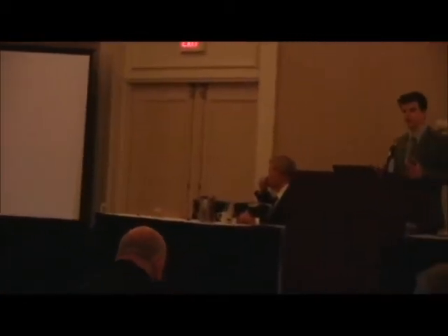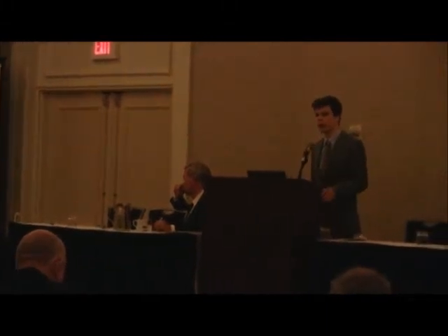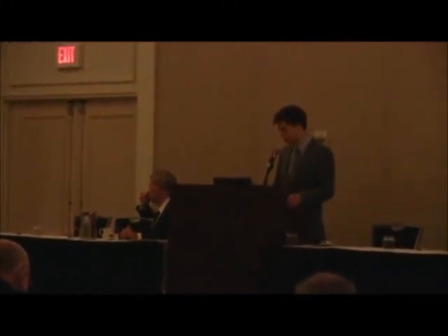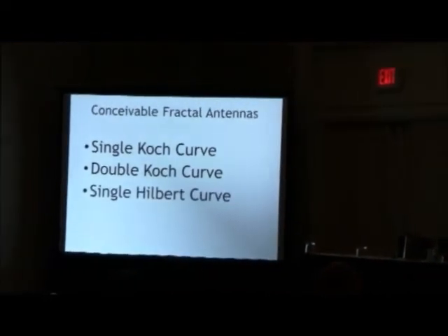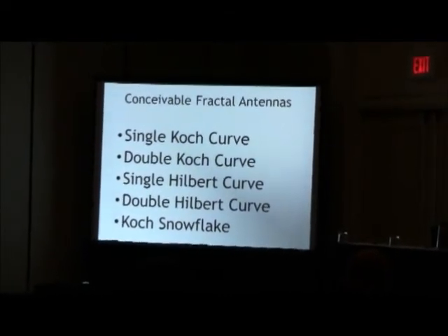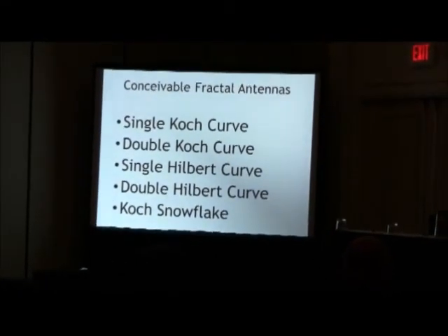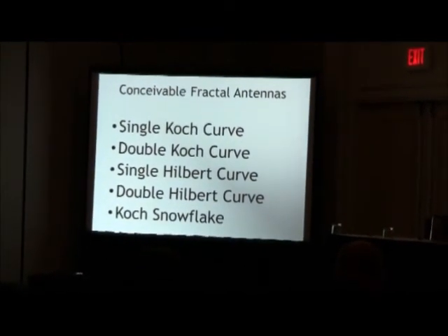In order to bring together the theoretical and practical aspects of designing fractal antennas, I wrote a program in the Python language that generates the coordinates of 5 conceivable fractal antennas and writes those coordinates to a special file called a .nec file that allows me to analyze and simulate fractal antennas.